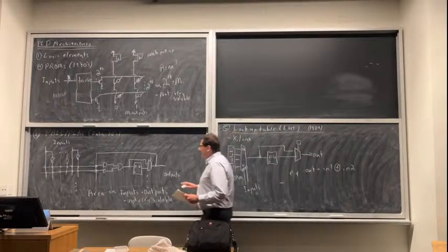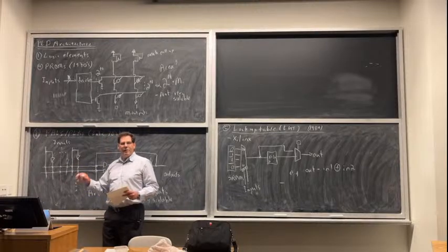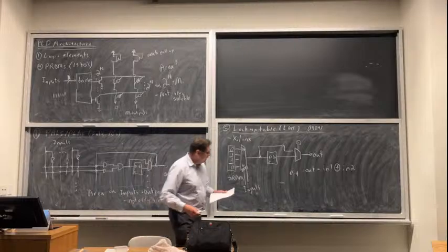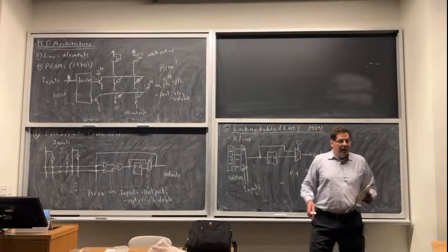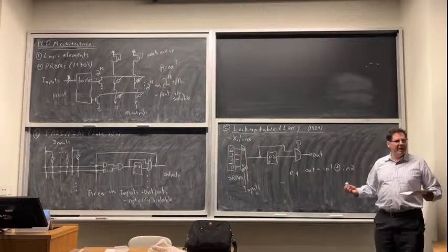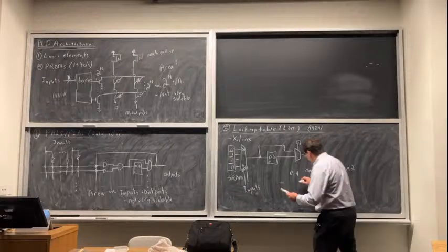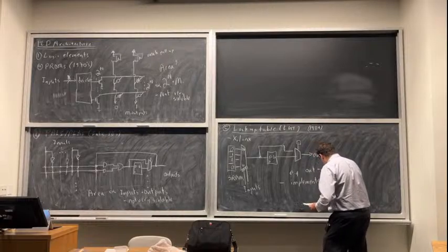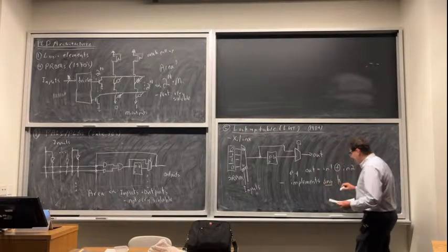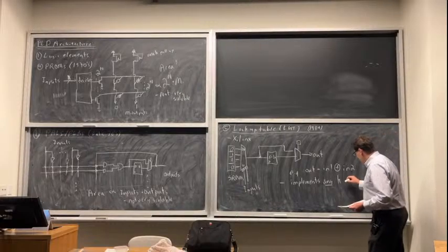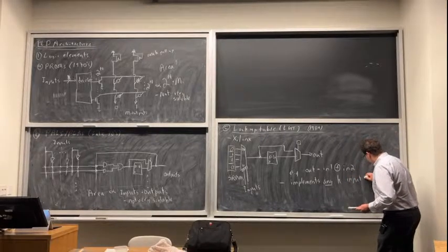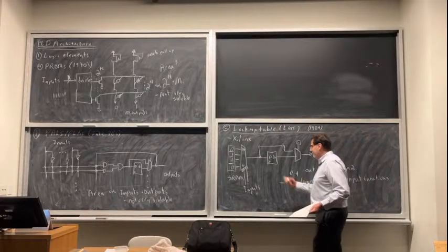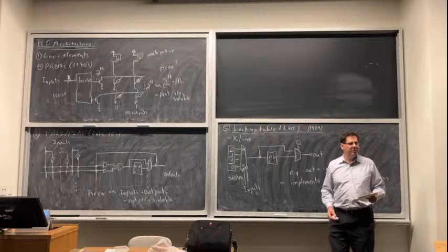This earlier structure can do some functions, if they can be decomposed into 5 input ANDs and no more than 2 inputs to an OR. So that does some functions with a certain number of inputs, but not other ones. This one can do any function as long as it has no more than k inputs. Here, k equals 2. So k is just the number of inputs.